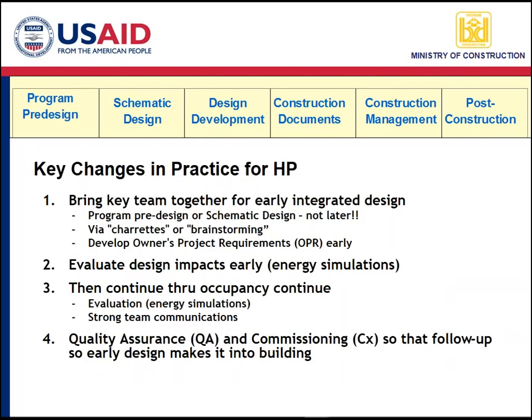So there are changes in design practice. You must bring the team together early. You must evaluate the design impacts using energy simulations early. We're going to be teaching you today and tomorrow on how to do that. And then once you do the early design decisions, you have to continue to evaluate throughout the design and construction process to make sure that changes are not made to destroy the design.